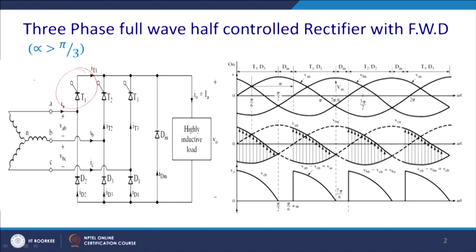What I wanted to say here is that we assume that your load current is highly inductive, thus you have a square wave, and that will be transmitted into the AC side also as a square wave.